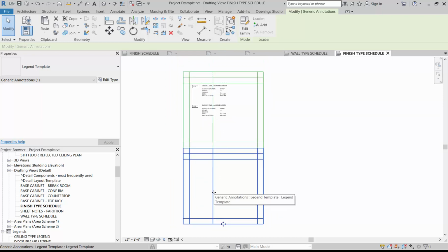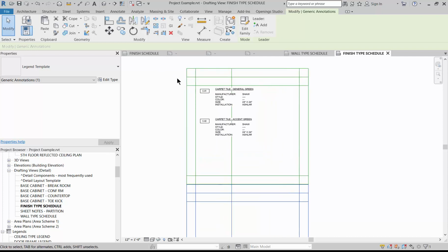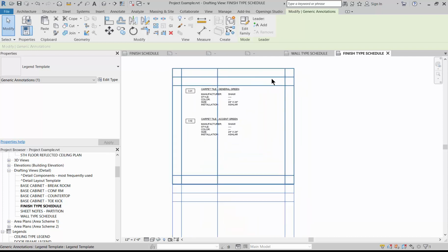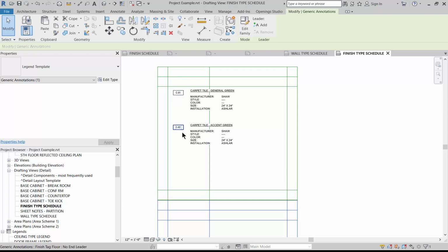It is usually going to be at least 2 high stacked or 2 wide stacked, depending which orientation you have. And again, just make sure you have at least 3 symbols. You don't need a symbol for ceilings, although you could create one, and you divide up your schedule by the order of, again, floor finishes, wall finishes, ceiling finishes, miscellaneous, and millwork finishes.